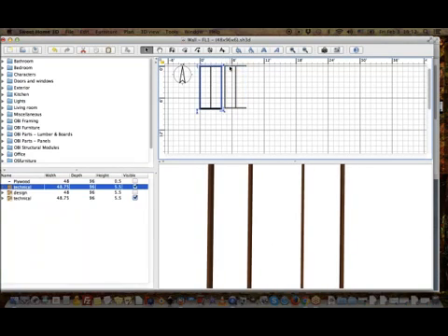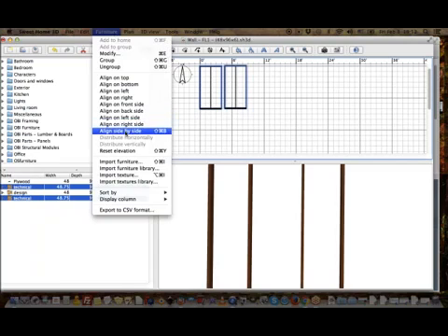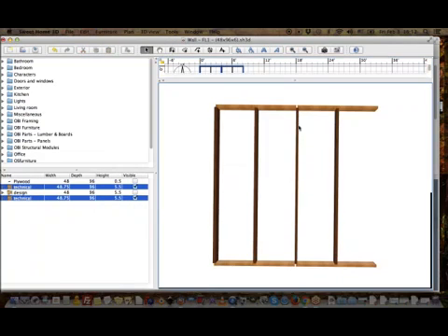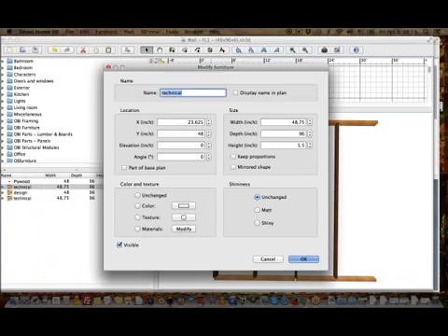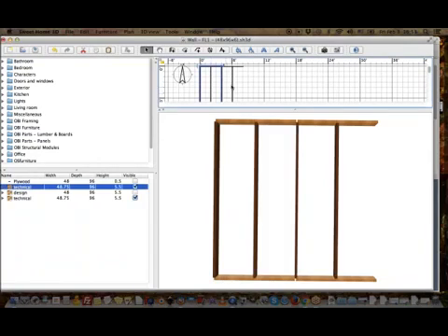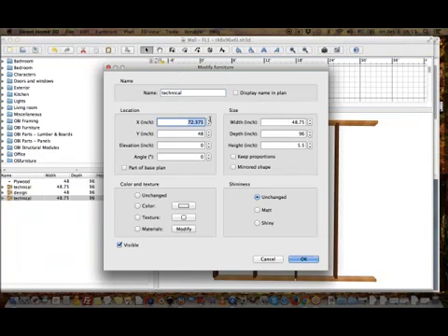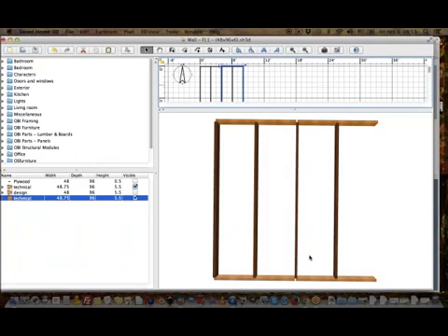Now I go to Sweet Home 3D, I select it like I showed you, and I do furniture align side by side. What happens is I end up with a gap here because Sweet Home 3D knows that my module ends here, and therefore it's not going to know that it needs to interlock. Now you could get into the numbers and move this one a 1/4 inch to the left. But once you have dozens of these, it's really, really hard to do, right? It's much easier to do a line side by side, and then the math just gets crazy and you spend hours on it.